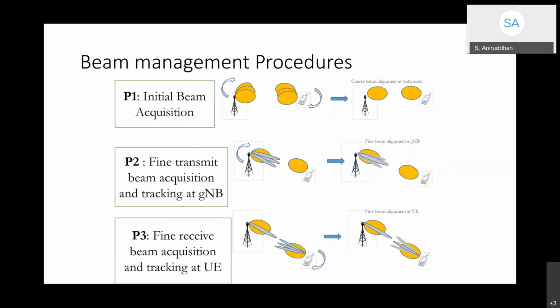So obviously this will also require things like acquisition of contact between the base station and the cellular user. So you can now start to imagine different scenarios. So obviously you are initially searching for the beam, then you do a coarse alignment, then you do a fine alignment, and eventually you start to transmit. So that is kind of the way in which people envision this type of communication will happen.